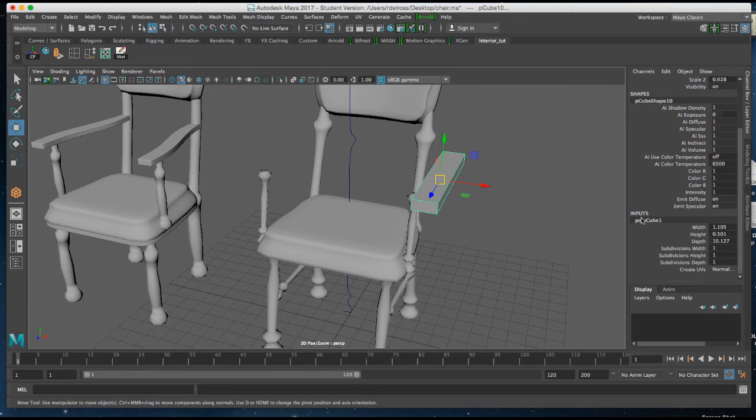I'm going to go over to my channels window now with my geometry selected, and I'm going to scroll down to that Inputs tab again. And if I don't see any sort of numerical values here, I would click on the geometry and we'd kind of wake that up, and then click on the word polycube as well. All right, so once again, I guess I'll make this 4. Hit Command S to save, and continue.